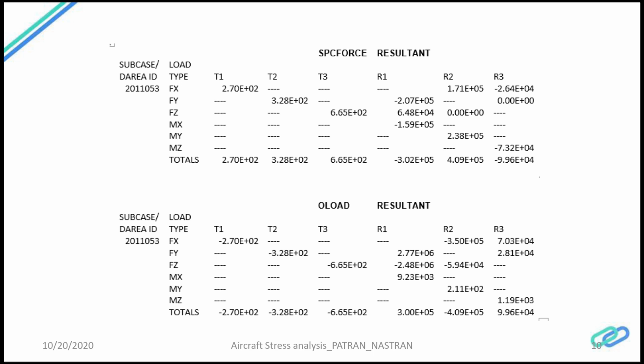So this is the force resultant and the applied load resultant. This is the constraint force and the applied load. Both are from the F06 file, just to make sure that everything ties up really well. So the applied load should be equal to the reaction force generated.